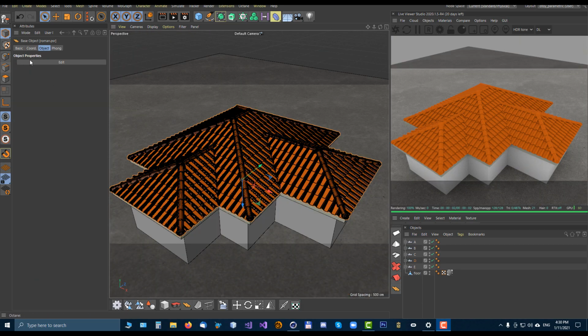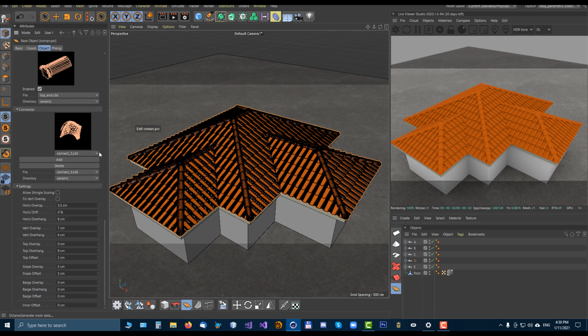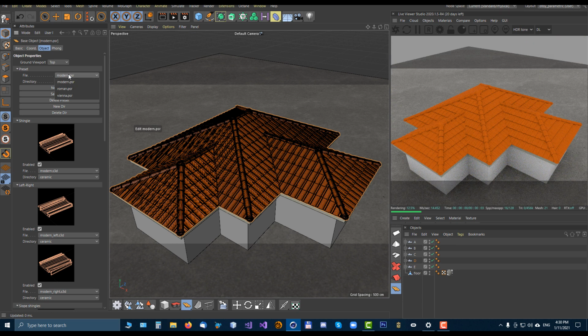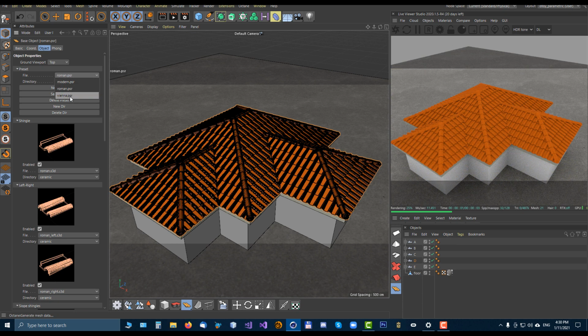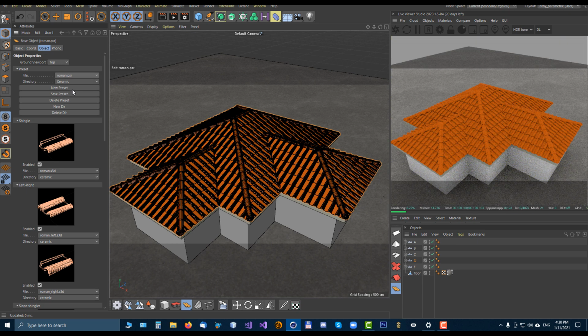And finally, the shingle tool is of course parametric. This is a bit complex parametric tool. You can choose between 3 already existing presets: Roman, Vienna and Modern. For most users, these 3 are pretty much enough, but you can create your own presets with your own shingles together with Add to Shape library. This is a bit complicated process, but it is doable.